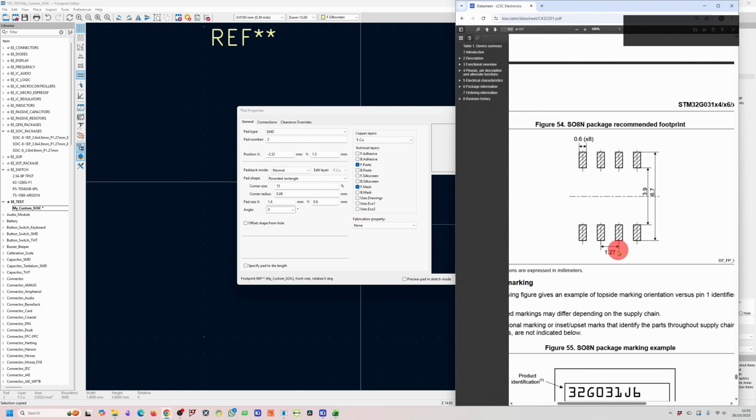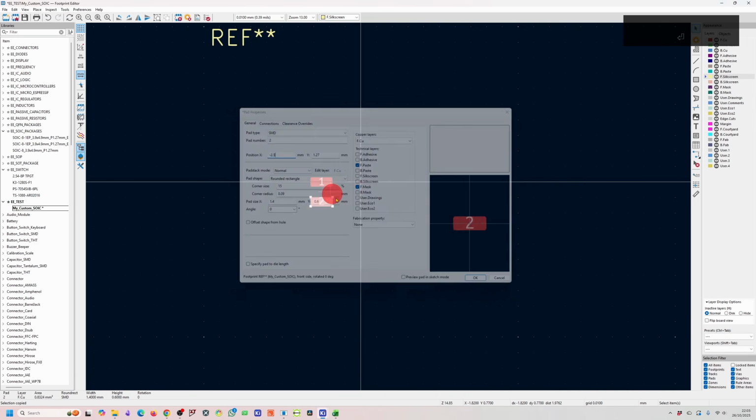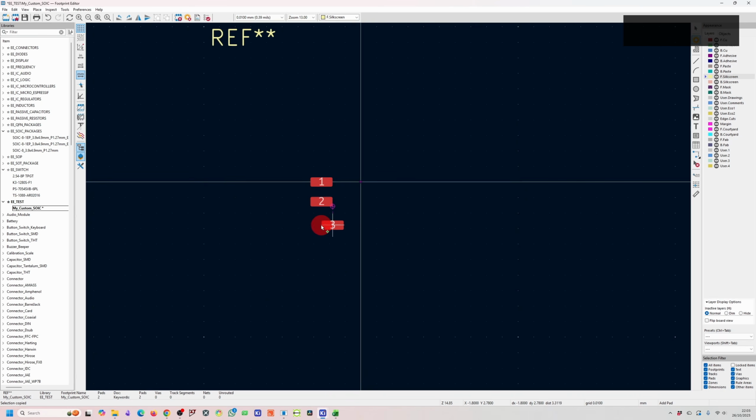So if you go back to the drawing, so obviously all of these pads are in a line, all of these pads are in a line, and they're going to be aligned this way as well. So we want to make sure we're following that. And the pitch is 1.27. So 1.27 on the Y and 2.5 over here. So let's keep placing our pads.